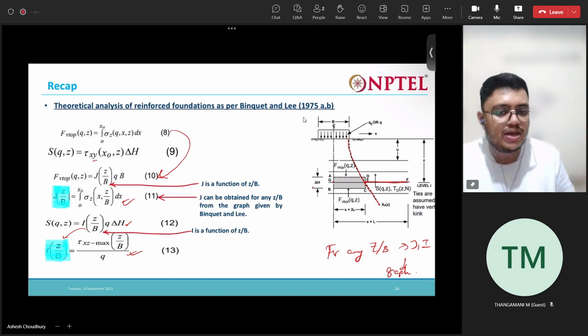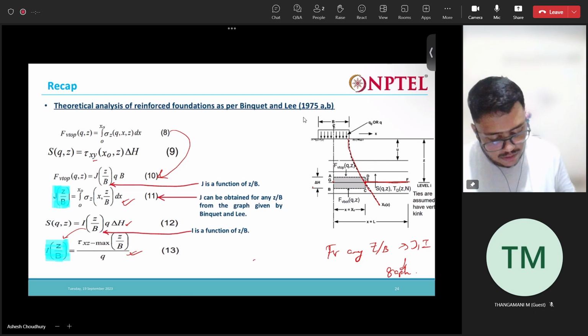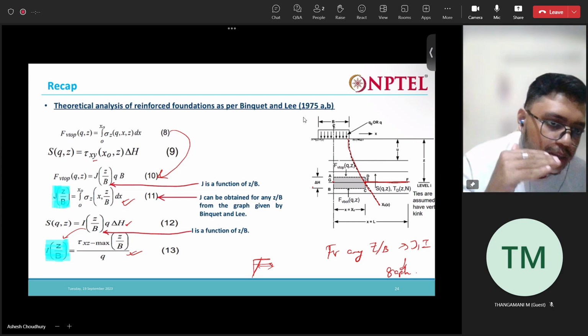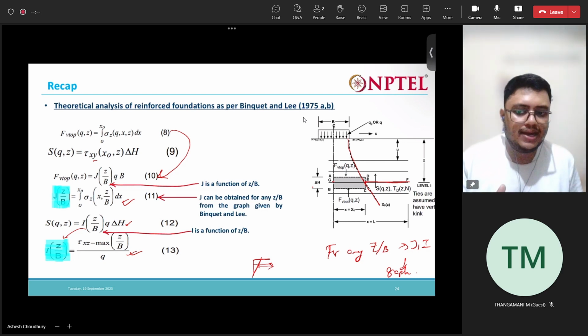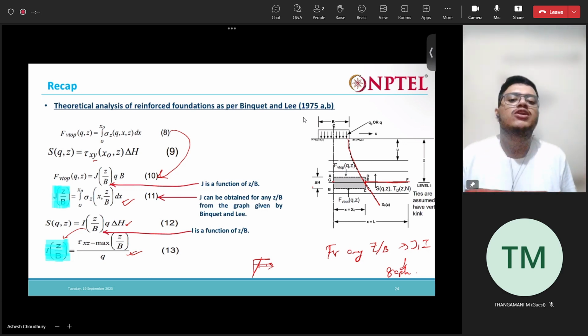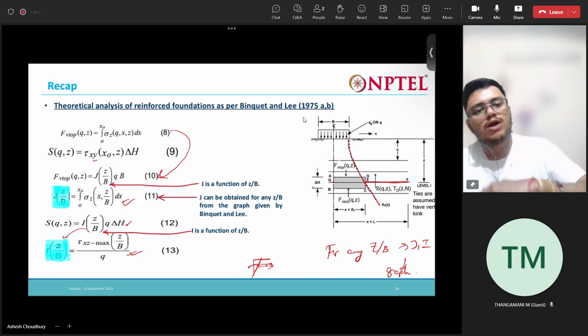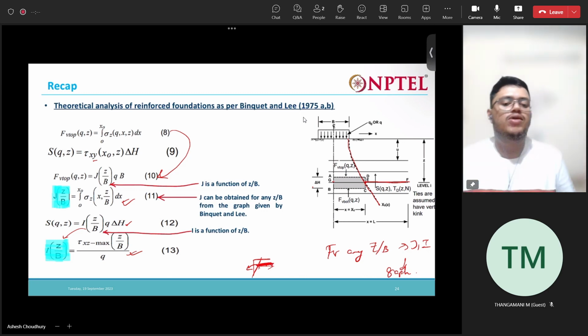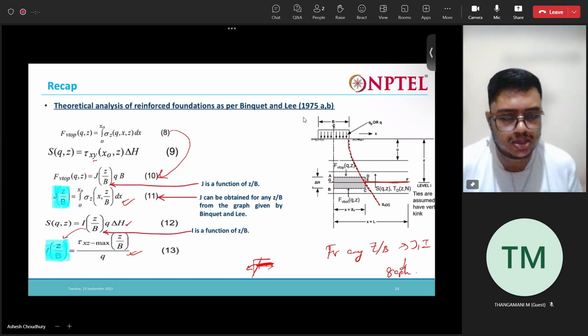So if you can recall, for the reinforced earth wall cases, here we had a wedge, then we had reinforcement. This length actually provided anchorage into the soil, right? This held the reinforcement in place. If this length is shorter, what will happen? Pullout failure will occur. The whole soil will fall down with the reinforcement. So the length of the reinforcement here is very important.